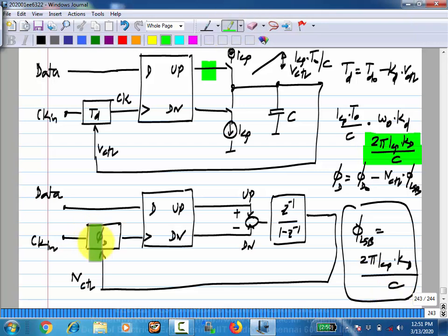You can try to implement, let's say, 200 phases so that it spans 2 periods, but that's a waste. Typically, this is a phase selection block and all the phases together will span 1 cycle. So if you go past 1 cycle, you have to wrap around and come back. If we make the phase increment 100th of a cycle, this has to wrap around after 100 steps.